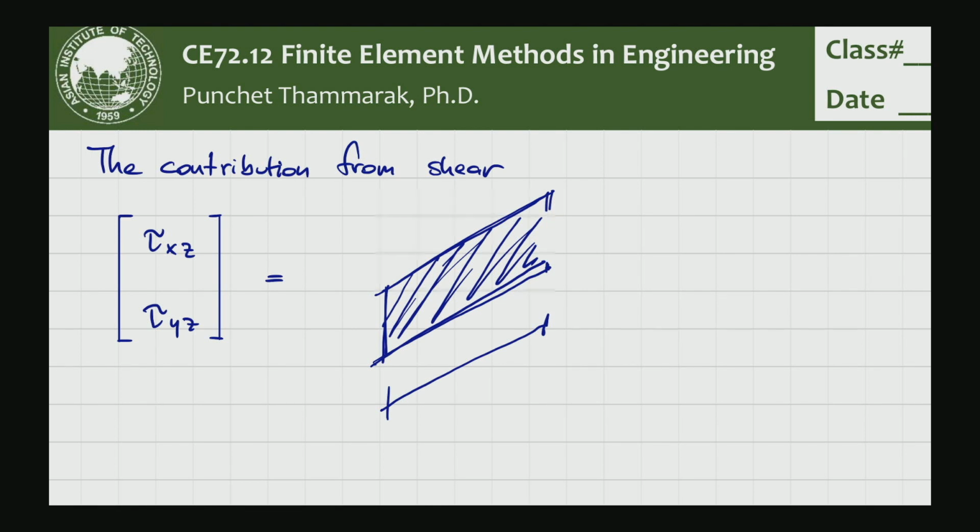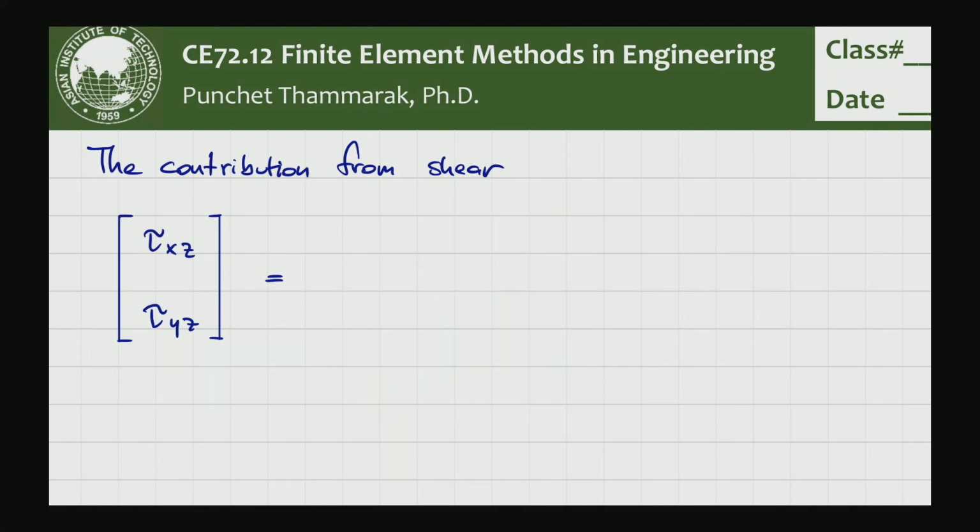When you incorporate the effects of the shear, you know that the shear distribution over the cross section is parabolic, and then you're going to need the shear correction factor K, which is 5/6, to change from the parabolic shape into a uniform shear distribution, because we cannot afford to have the precise shear deformation like in the real problem.